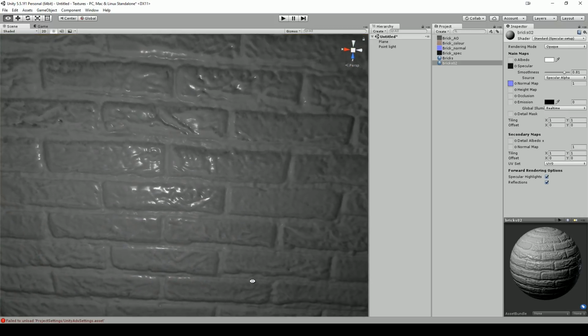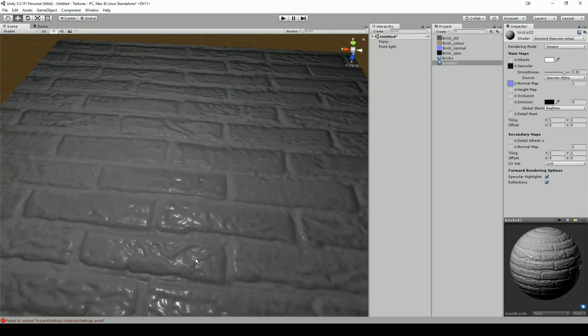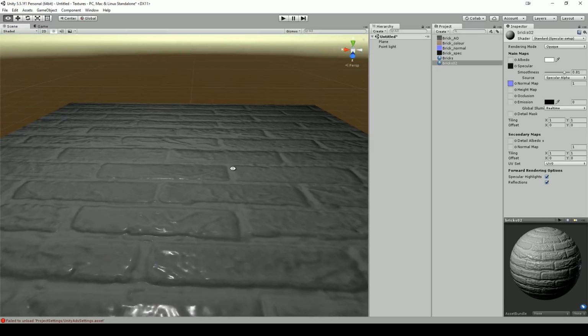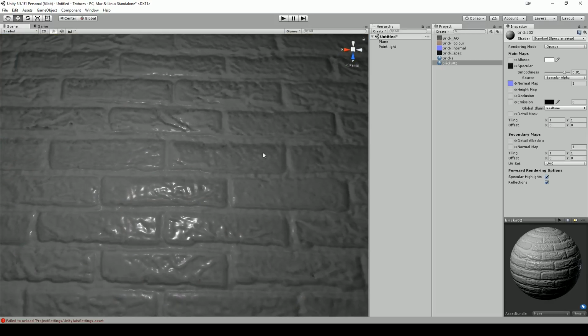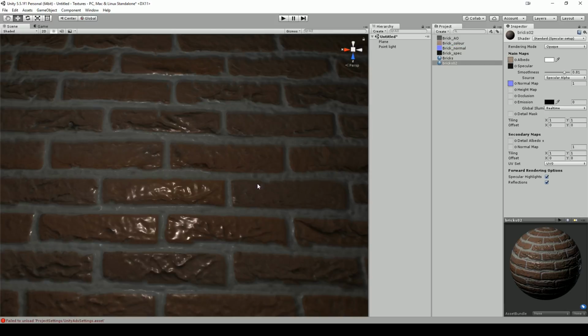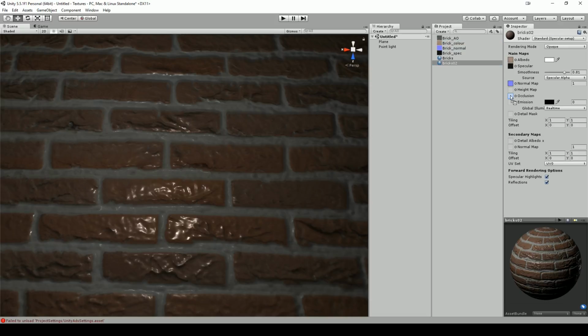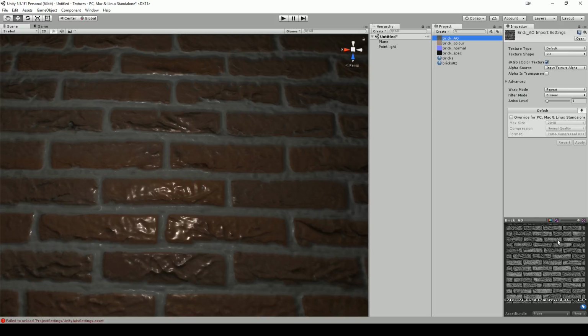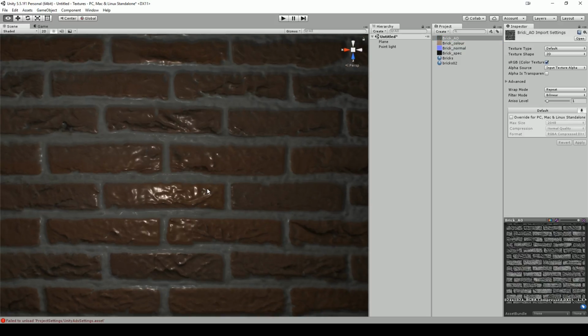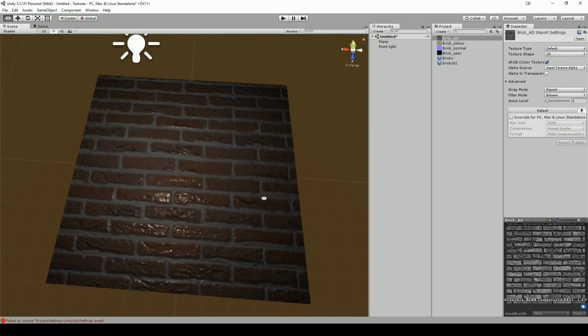And you can really see the detail there as I turn it. It's creating shadows to give the impression of all that extra detail. The color just goes into our albedo, gives us our color, and the AO, which is the black and white one, goes into occlusion, so AO for ambient occlusion. And that was quite a subtle effect, mainly because I didn't make this dark enough, to be honest. That could be a lot darker to push that grout. But that's the real-time renderer.